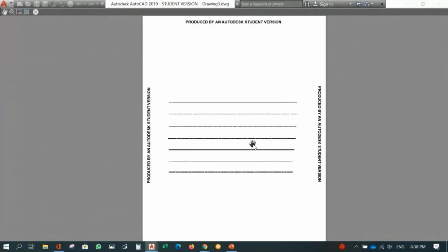So as you can see, now the line thickness appears here. All this line thickness is important for technical drawing, whereby if you do not apply line thickness according to the correct line function, mark deduction will take place.